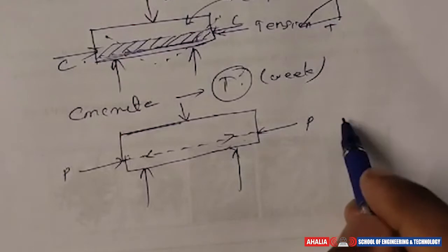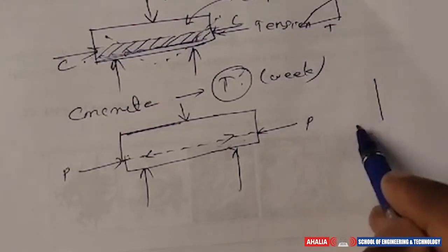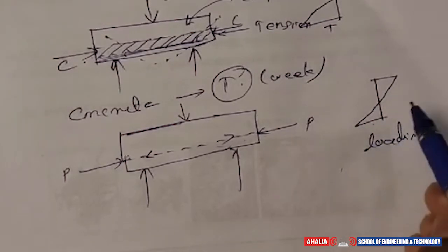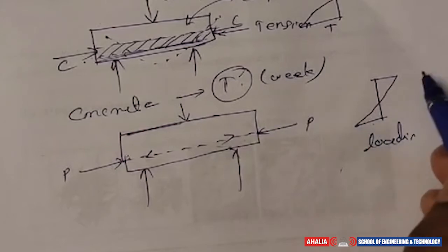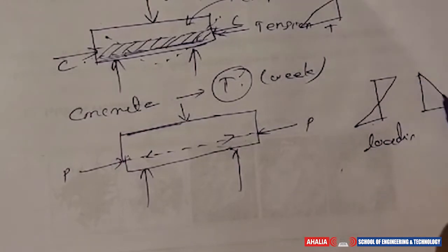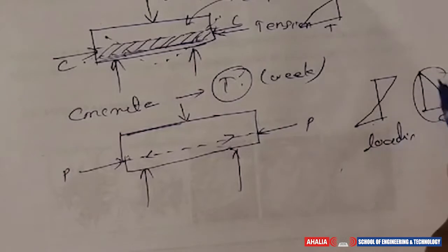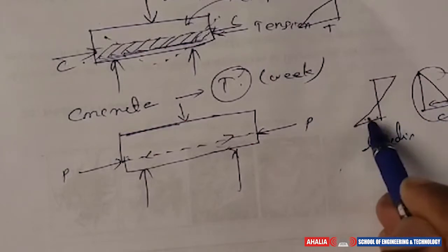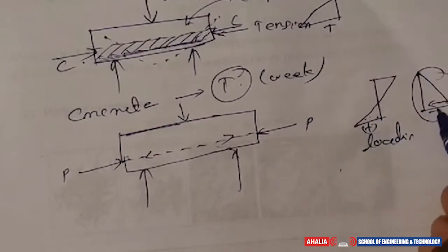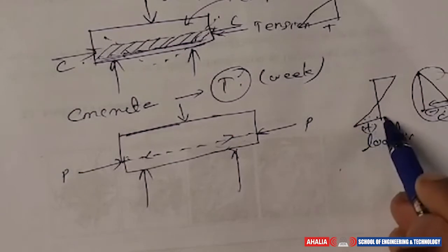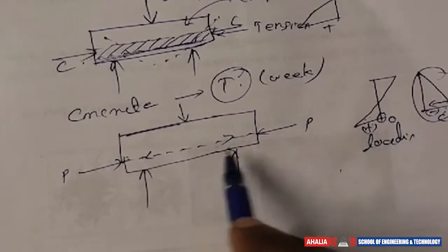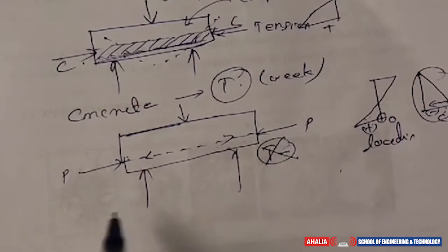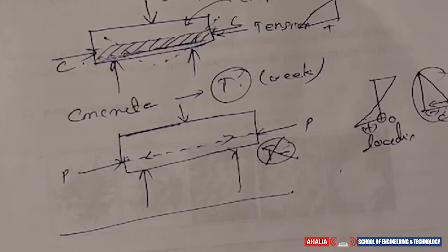act here. At the time of loading the stress would normally be like this, but in this case we already have a highly compressive force here. So when the tension acts, this compression will be reduced, because if we take this as positive and this as negative, it is an opposite action and it reduces, at maximum to 0. So it will not go to the tension zone. So tension we can avoid. This is the principle of pre-stressed concrete.